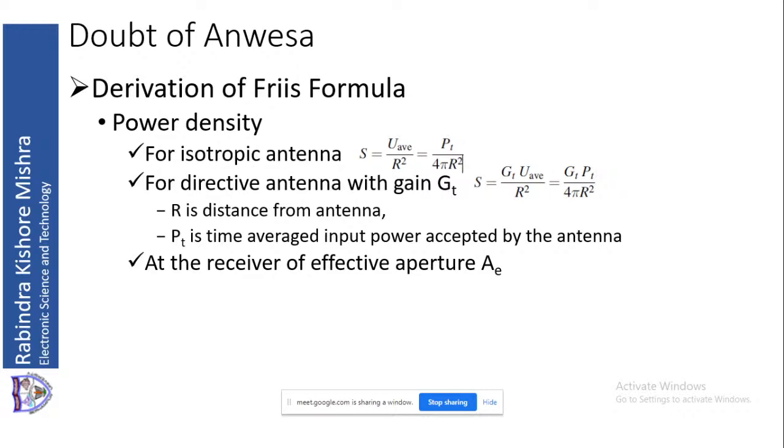But the receiving antenna will not be that large. It will be smaller than that. So the aperture of the antenna will receive a smaller amount of energy, not the complete energy. Suppose at a distance of 1 kilometer, we have about 750 meters of aperture for the total energy, since 1 degree covers 750 meters. Your antenna will be about 1 meter maximum. So 1 meter will intersect only a 750th part of the field of power that is coming, right?